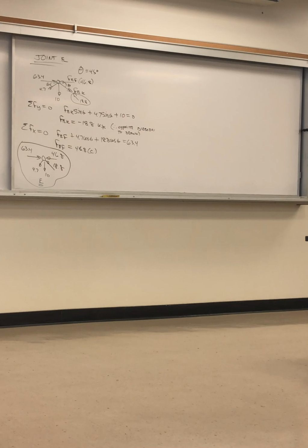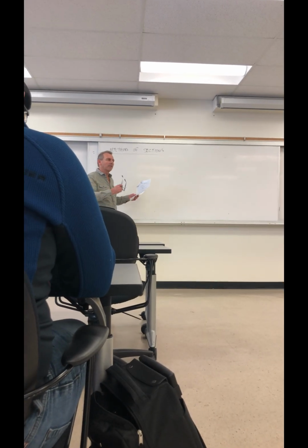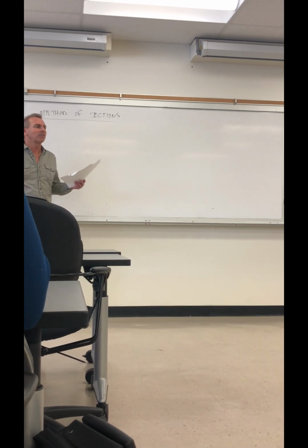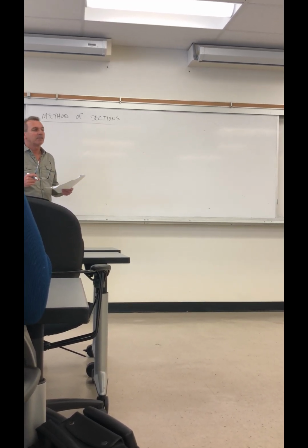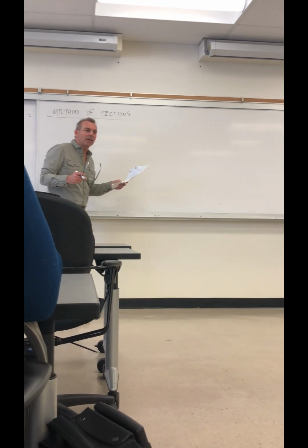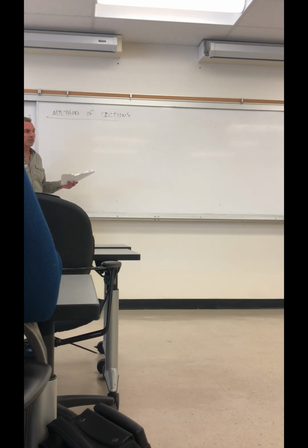Okay. Talk about method of sections. It also gives you member forces for a statically determinate truss, like the method of joints. Completely different method, but since it's based on overall statics, you're getting identical results. It has different applications. Method of joints is when, as we saw in the prior example, you want to solve for all of the member forces, every one of them, in your structure.